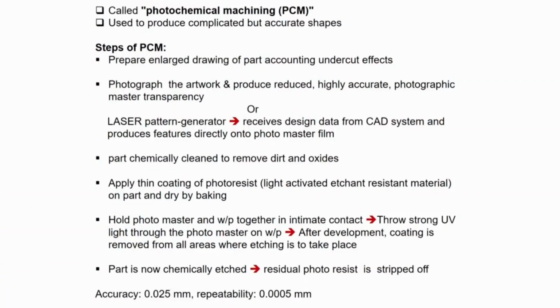Nowadays computers are used: it takes the CAD model into the system and produces the features directly onto the photo master film. In earlier days, an artist generally made this bigger size, then it was reduced and made on a photoresist or photo master film.